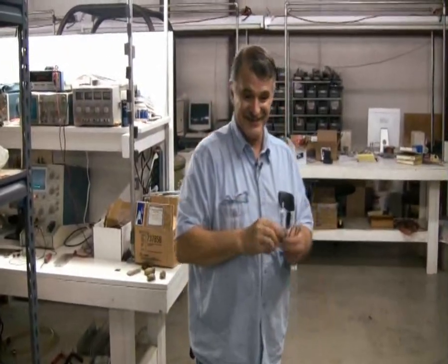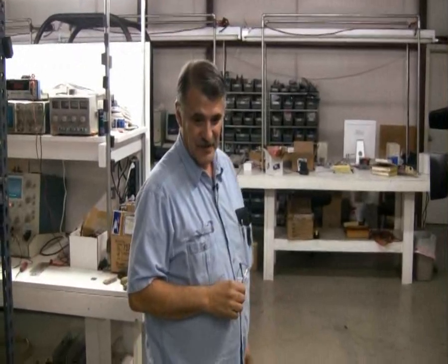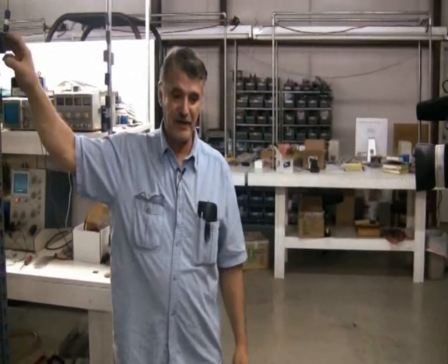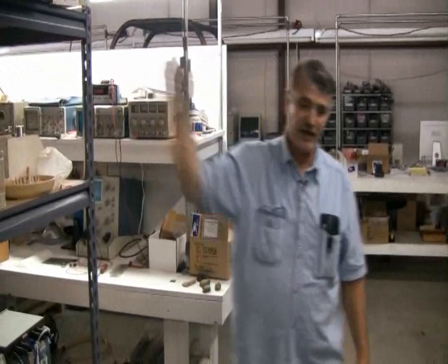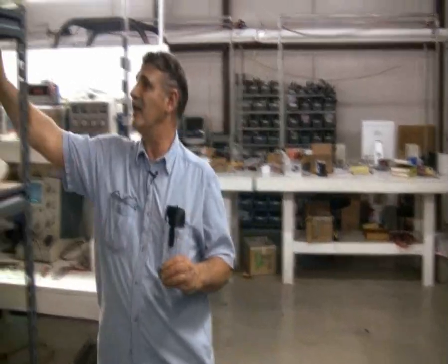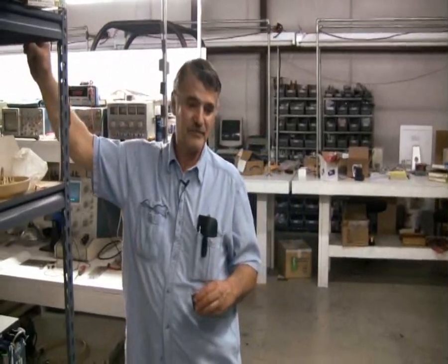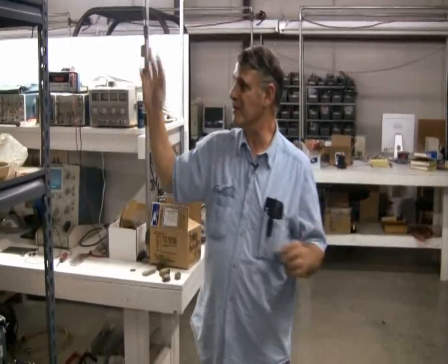Okay, let me tell you something. I've got a magnetic clasp on my medicine cabinet. It's a little magnet that's inserted in the door, and it's lost its magnetism. It's probably an old Alnico. I don't know. The only way a magnet can lose its magnetism is if it didn't have a keeper on it and it was an Alnico. But this magnet cannot lose its magnetism. Now, take the neodymium iron boron magnet, just get it warm and it'll lose its magnetism. As soon as it reaches its Curie temperature, it's gone. Your free energy is gone.